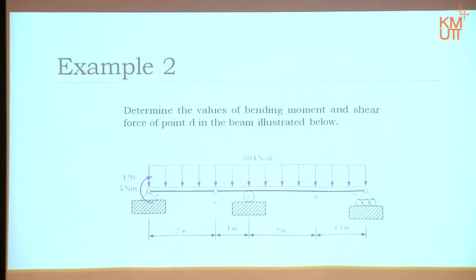What I want here is the shear force and the bending moment at point D. With this system of calculation, you generally need about 8 equations to get to the answers. With full equilibrium, right? Well, with virtual work, one equation per value. Therefore, with virtual work, you need only 2 equations.